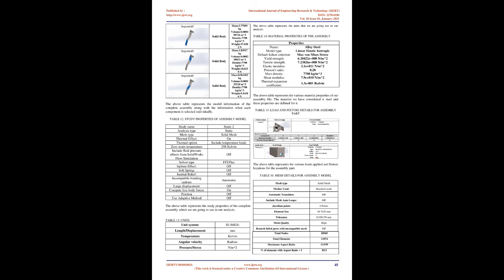SolidWorks offers 3 types of assembly motion simulation. 1. Animation is simple motion simulation ignoring the component's inertial properties, contacts, forces, and similar. Its use is suited for the verification of the correct mates or basic animations, for example. 2. Basic motion offers some level of realism by accounting for the inertial properties of the components, for example. It does not, however, recognize externally applied forces. 3. Motion analysis is the most sophisticated motion analysis tool, reflecting all required analysis features such as inertial properties, external forces, contacts, mate friction, etc.